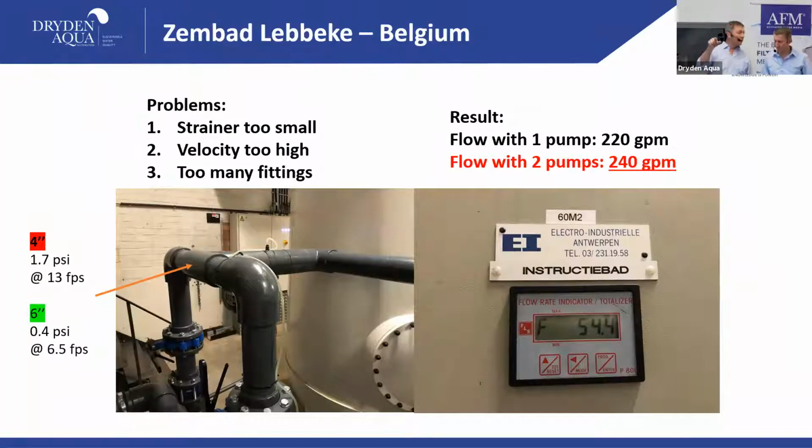Maybe you can explain the 1 T. Yeah, so we're using the 1 T here, a 4-inch T, which gives us a pressure loss of 1.7 psi, just that 1 T. Remember, at that high velocity, the lambda that we have is 1.5. It's the highest lambda that we have. Exactly. So if we just change that T to a 6-inch, the pressure would drop by half. And we talk about 1 T. Okay, and it was measured. Not with Flowsys, but with this, that works as well.